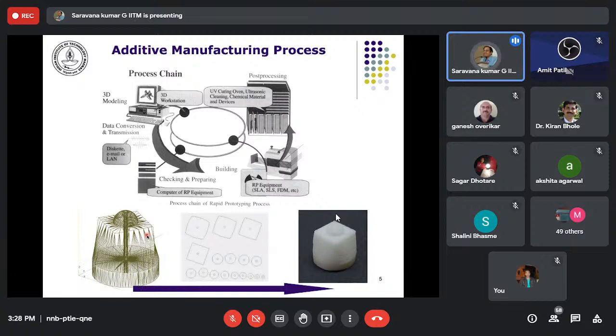And it is possible with newer file formats like AMF to have what we call the bicubic surface patch, wherein the error, not only in the absolute deviation but also in terms of higher order information like the curvature or the normal, can be handled.